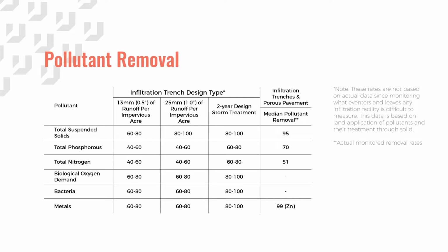This chart from the Interlocking Concrete Paving Institute, ICPI, design manual displays the increase in water quality as a result of permeable paving practices. Permeable paving fares well with most contaminants, but does fall short with de-icing chemicals that are commonly found in road salt. These de-icing chemicals make their way through the system due to their fine size.